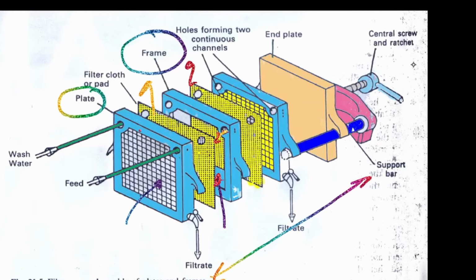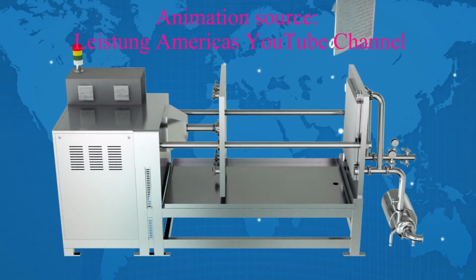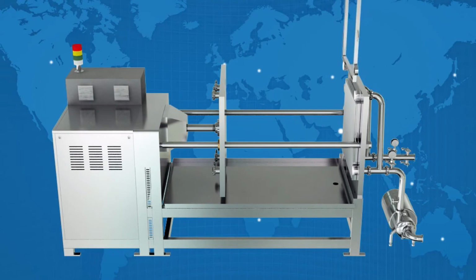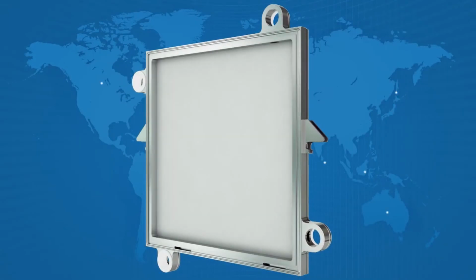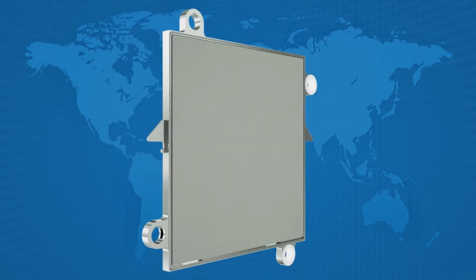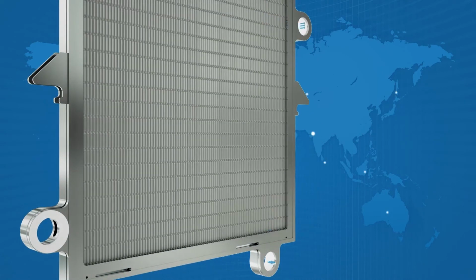The liquid comes out on the plate side, and on the plate side there is this opening here to collect the filtrate. There may be channels for filtrate collection on individual plates, or there can be a common line to collect all this filtrate. So again, the operation is like this. Plate and frames are arranged alternatively, and there are filter media on both sides of the frame, and that filter medium allows the liquid to go through, and when liquid comes on the plate side, it's collected from there. The solid continues to deposit on the frame side, and after some time the solid needs to be removed. So that's why you need to dismantle the press and collect the solid from the frame parts. That's the summary of this filtration operation.